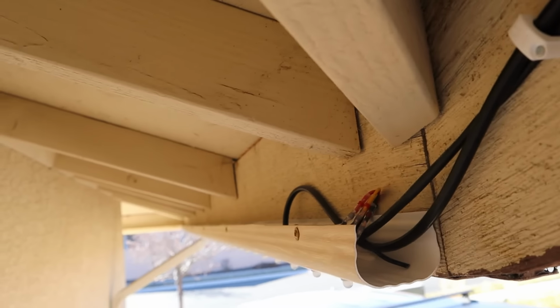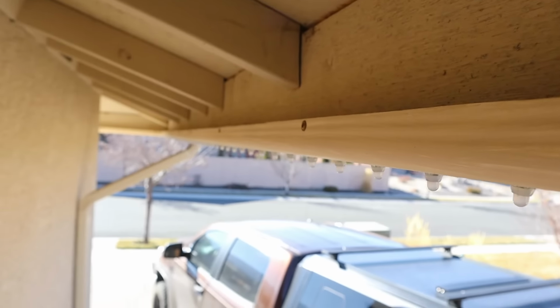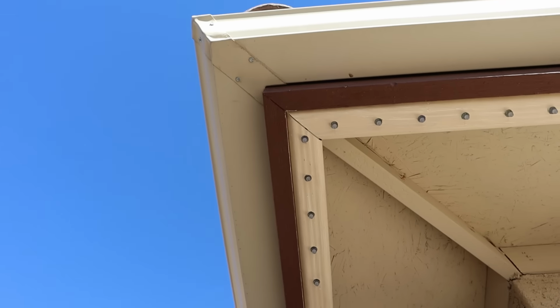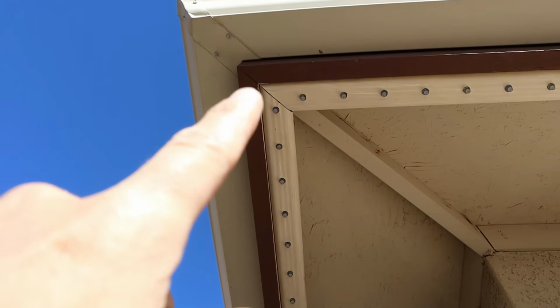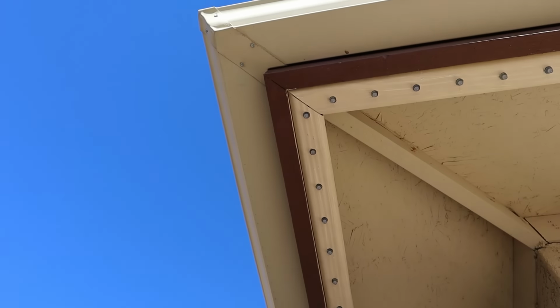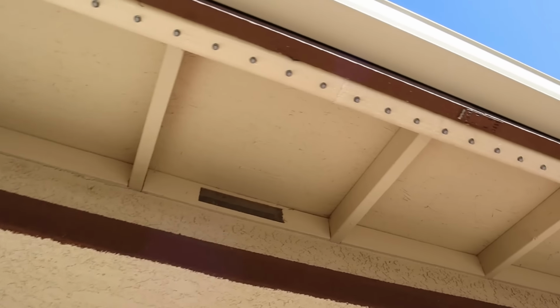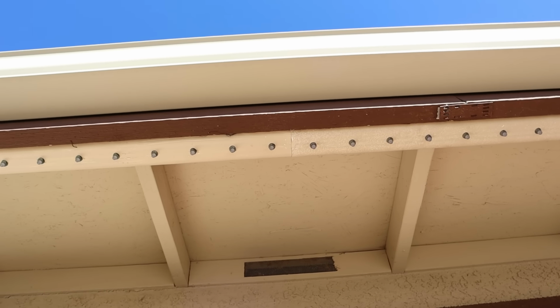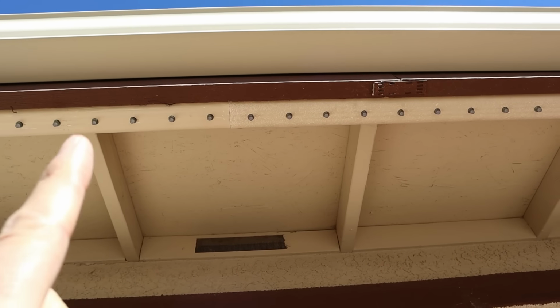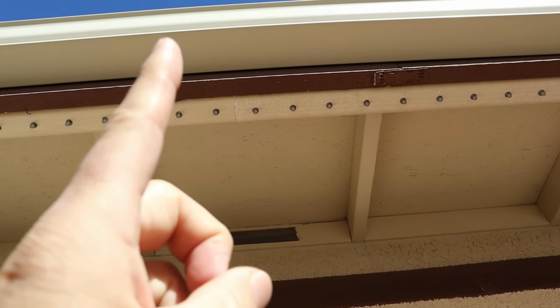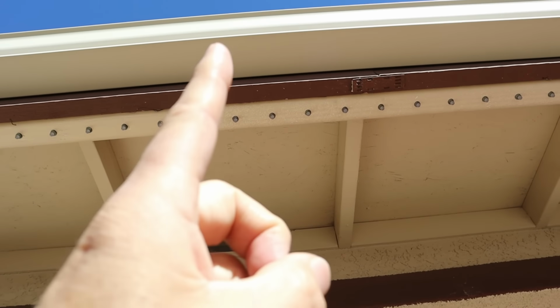But that's what it looks like on the back of the fascia, and you can see those little pixels are sticking down just a little bit below, and overall pretty easy to mount. Every time I came up to a corner, I just cut a 45 with my miter saw, which was pretty easy to do. And then when you get to the end, as I mentioned earlier, I do 1 3/8 from the last pixel on each piece, and then I start the new one at 1 3/8 so that they're evenly spaced apart, where you have two pieces that butt together.